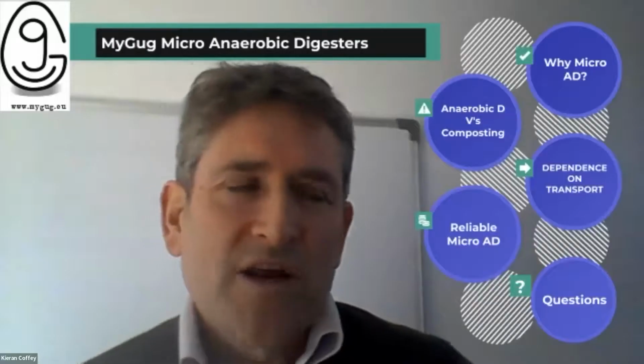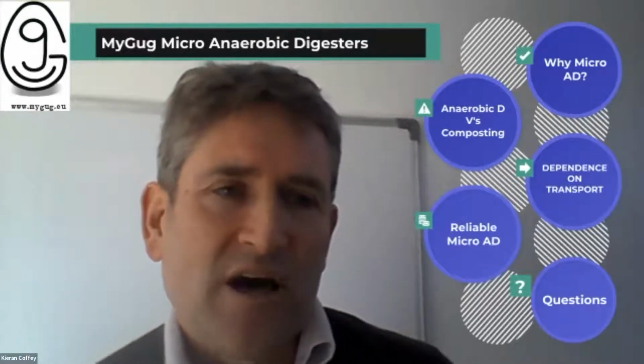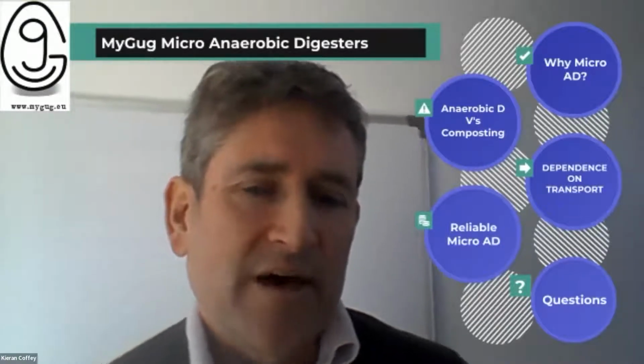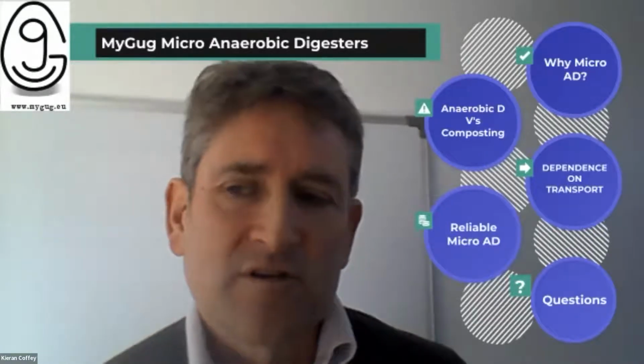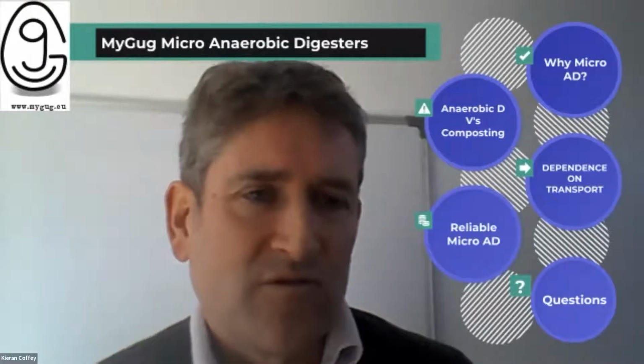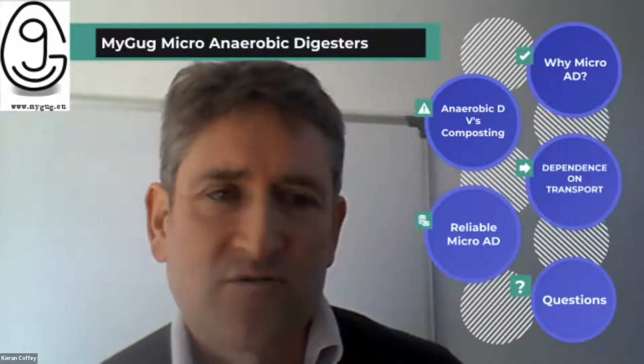Enrico, another question. Do you do a feasibility analysis to understand what size is needed? Also, what about the type of bacteria? Well, generally for a household, part of the European study said that each adult will produce about 92 kilograms of food waste. So we base our figures on that. And for restaurants and commercial outlets, they'd have to see how much food waste they're producing to understand what size of digester is required.